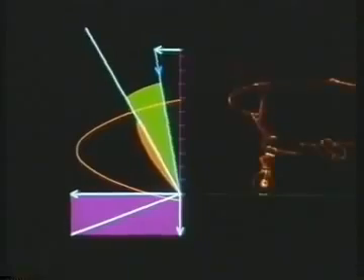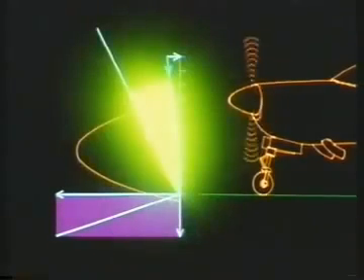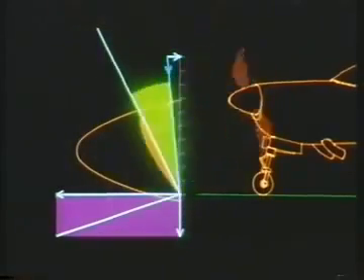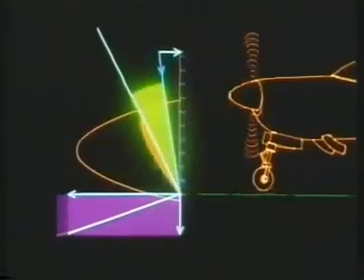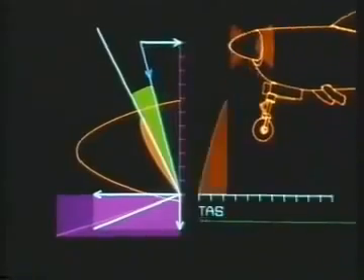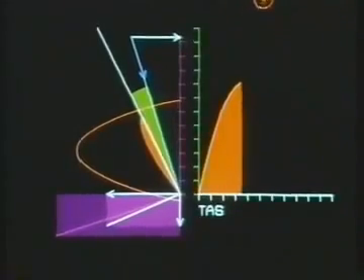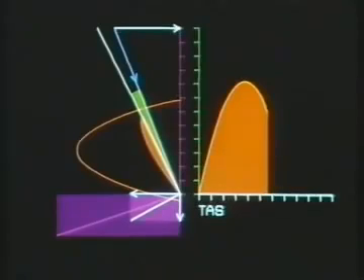When a propeller is turning at a constant speed and the aircraft is stationary, the angle of attack is big, and large amounts of thrust and torque are produced. As the aircraft accelerates, so the angle of attack decreases with a consequent loss of thrust and torque. This continues until the reducing thrust equals the increasing airframe drag, when the aircraft has reached its maximum speed.